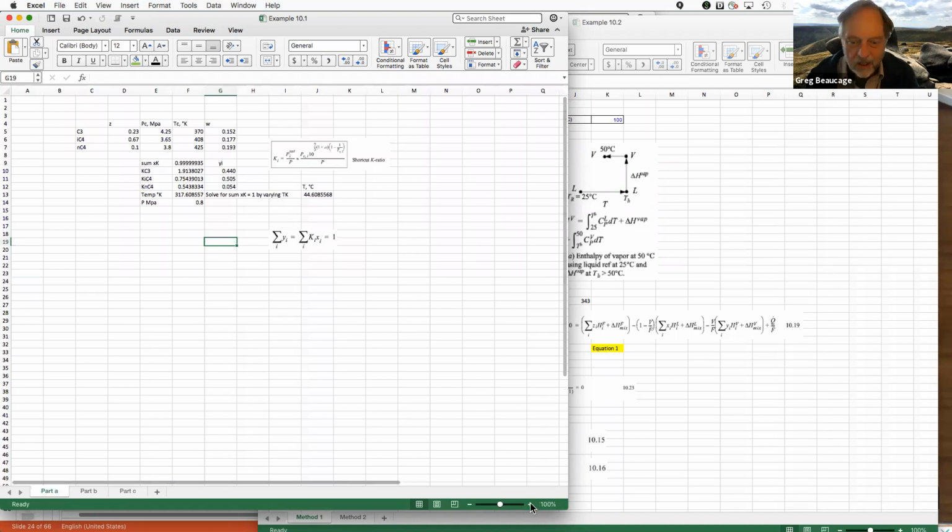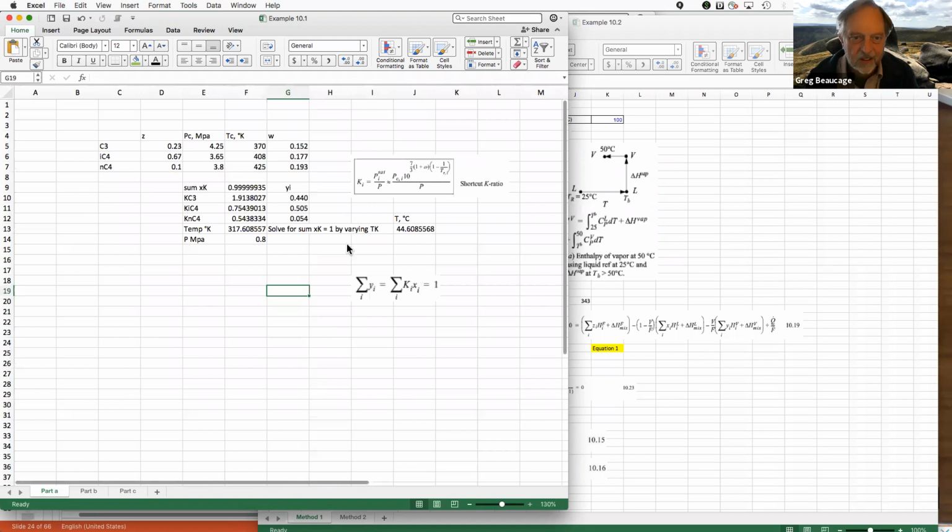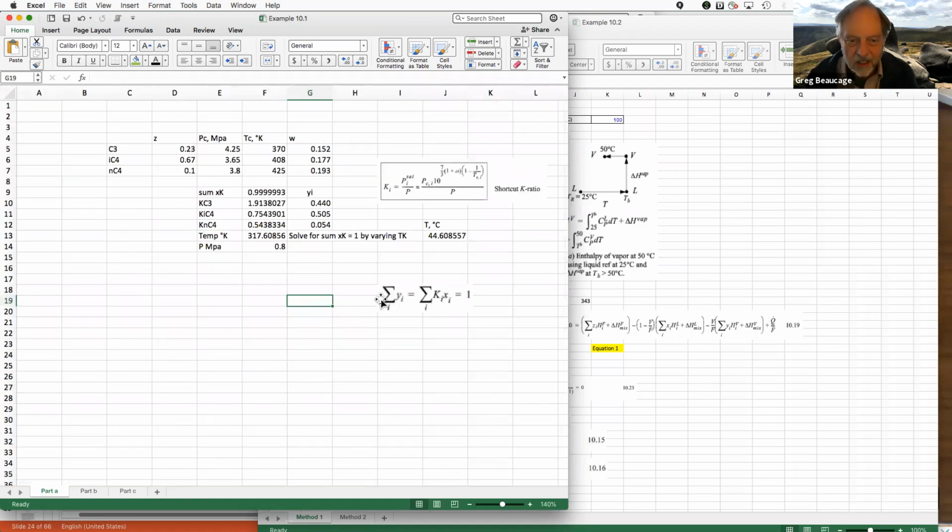Right. So this will increase there. All right. So we're boiling. We want to get the first point where it'll turn to liquid. That's the first point where it starts to boil. So that's the sum of y equals 1, that's Ki xi. This is K here. There are 3 components, propane, isobutane, and butane, right? So I have the Ks for those here.